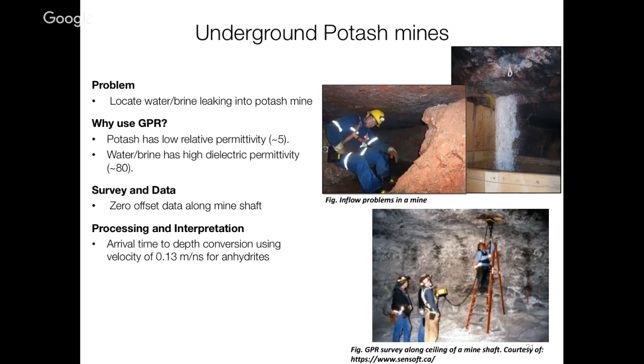Here's another application we were involved in. This too, it's a potash mine in Canada, in Saskatchewan, and there the big thing is water. So remember, water had this really high electrical or dielectric constant. That means that you get a strong reflection from it. And now, of course, you're worried about water coming in from the ceiling. So you have to do the experiment where you put the GPR system up on the ceiling, right? And now you're walking along like that. And then you're looking for reflections and trying to see where the water is.